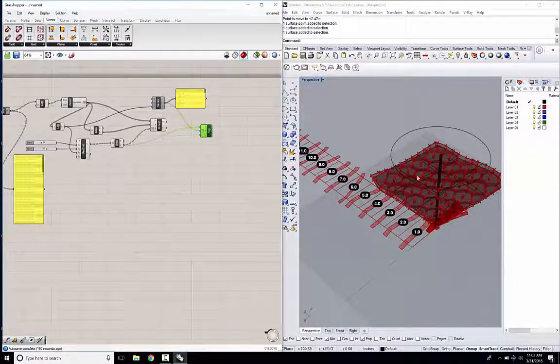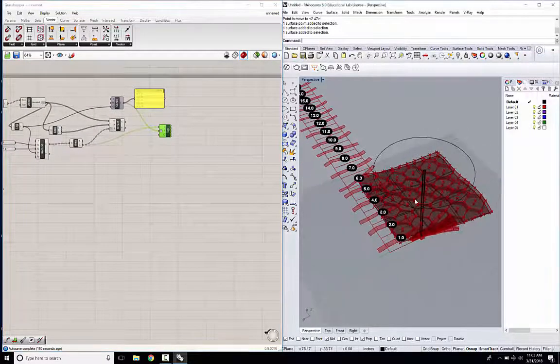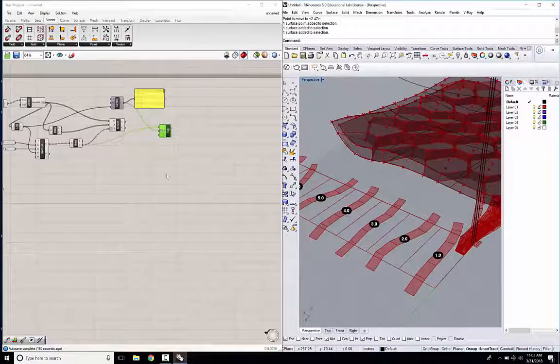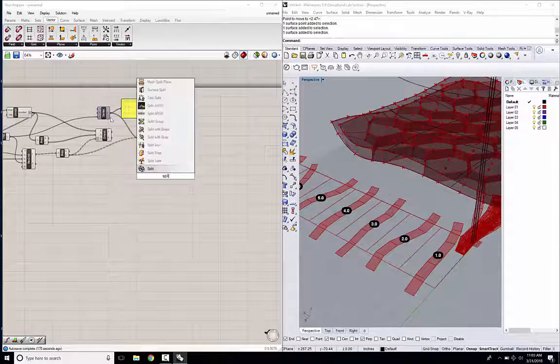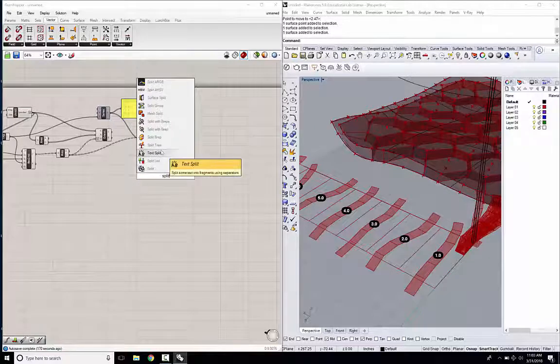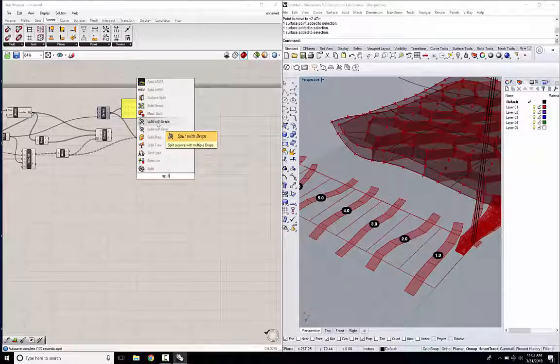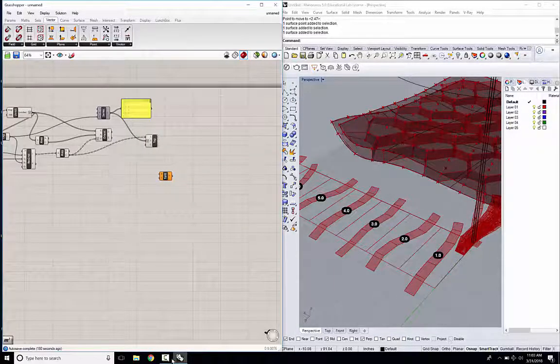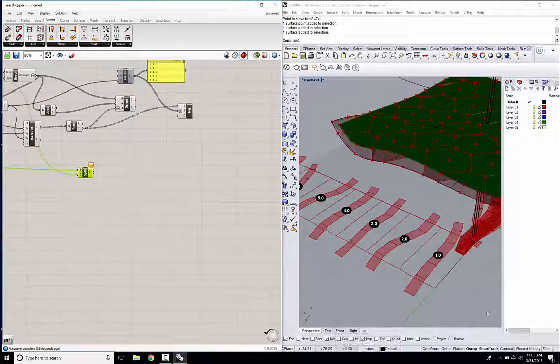And then if we want to do the same thing to the objects up here, it's easiest done if first we split the surface up based on these objects. So I'm going to take a split. I think we want to use a B-rep split. Let me just make sure this works.